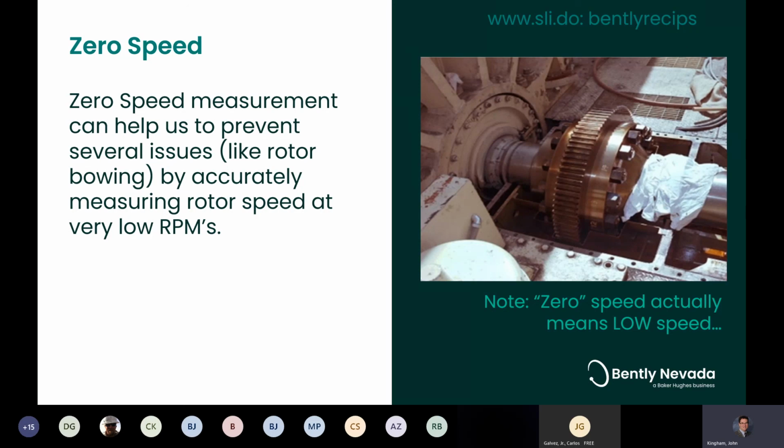We'd hurry, put the weight in the proper location, and then we'd rotate the shaft 180 degrees. And that same guy would restart his stopwatch, and when we hit the same time that we had been sitting there before, we'd start the unit on turning gear.